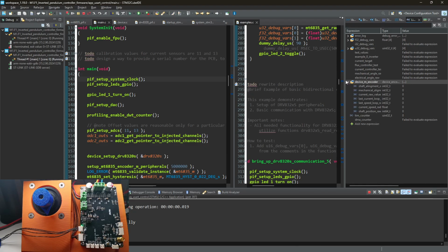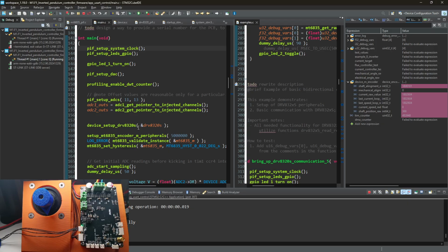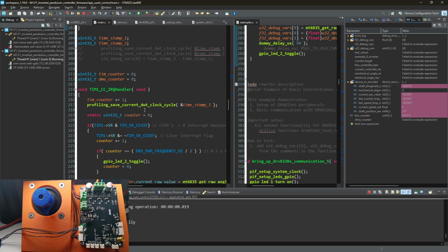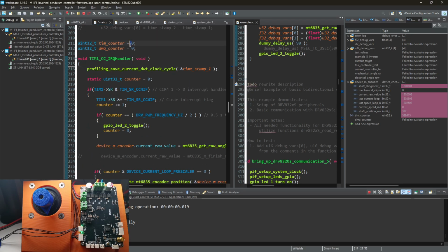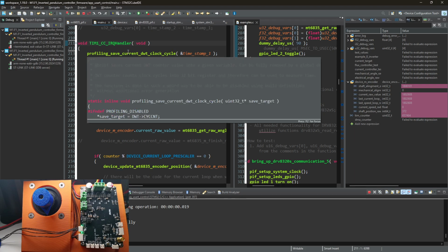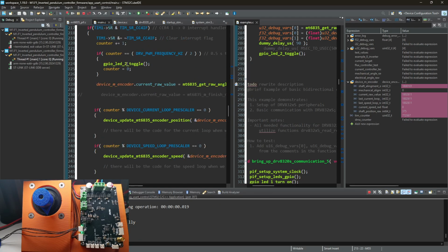So we do calibration, sure. And we have values that look good enough. They are relatively stable. There is a drift of sorts, but a single bit in a 21-bit encoder is not a huge issue. I'm absolutely fine with that. Okay, so it works. It does work indeed. Hooray! Okay, let's remove this and that. And let's try to use the next hour to actually implement FOC of sorts.